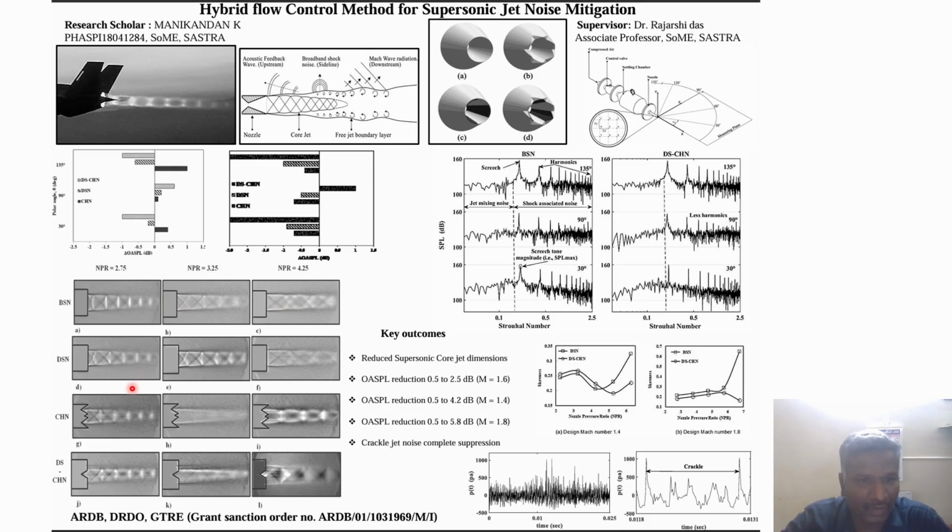But moving on to the modified nozzles, the chevron and the deflected seal chevron are giving the highest perimeter jet immediately at the nozzle exit. It is a clear indication that a higher perimeter is likely to increase the interaction with the atmospheric air, and better interaction means more shear layer development and reduced jet noise. At the front we can also see the induced vortices from the chevrons appear as white streaks. Finally, when I couple the chevrons with the deflected seals, the jet comes with the highest perimeter, and overall a shock cell length and shock angle reduction was observed.